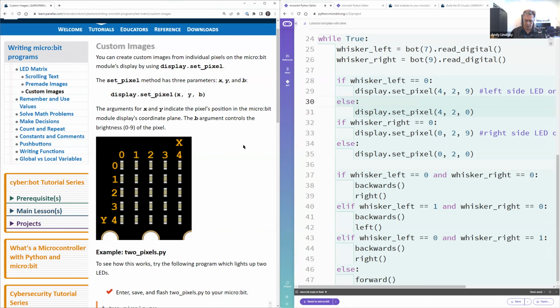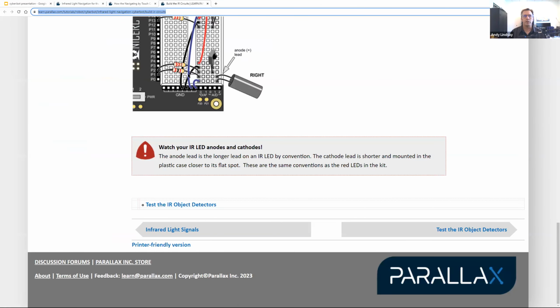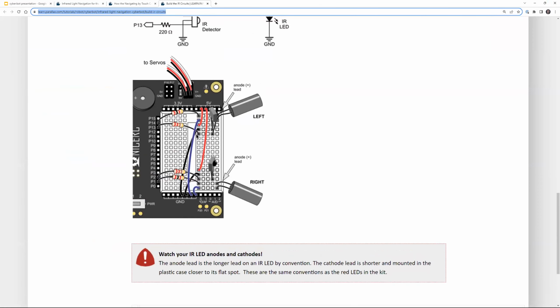Okay, welcome back, everyone. Stephanie, you said you had a couple of questions that appeared in the chat. Yep. Is it best to just use non-rechargeable batteries? Oh, no, it's fine. Usually, if you're using rechargeable batteries, I recommend nickel metal hydride, NiMH. I'll talk about that a little bit because we have some that we like at Parallax. The main thing is to go with a high capacity rechargeable battery that can store enough to run the robot for a good long time.